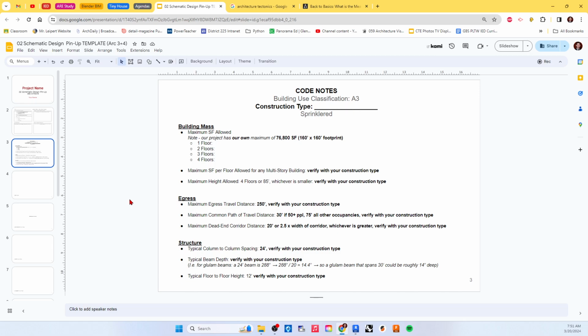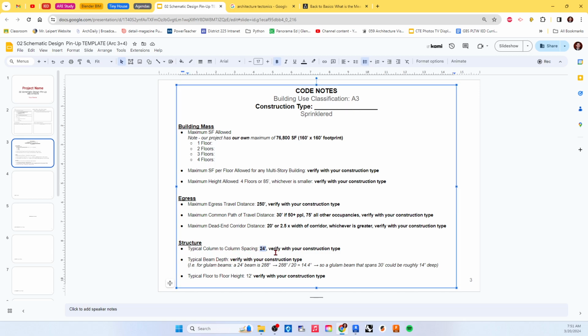If we did a heavy timber building, there's a general rule of spacing that is about 24 feet column to column. If we did 24 feet column to column, we're going to be around 14.5 inches deep, which basically means that your typical 12-foot ceilings would work pretty well with a 24-foot span. However, if you wanted to go longer than 24 feet, you are more than welcome to.